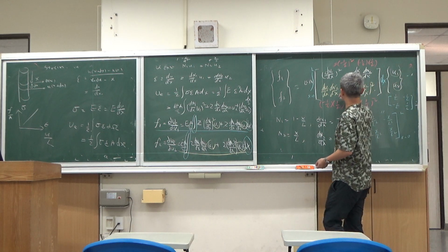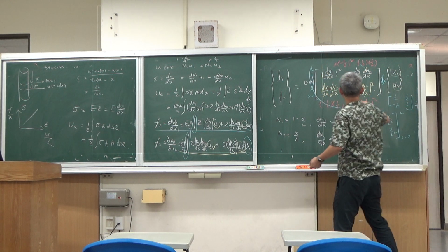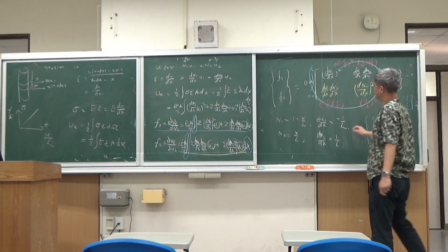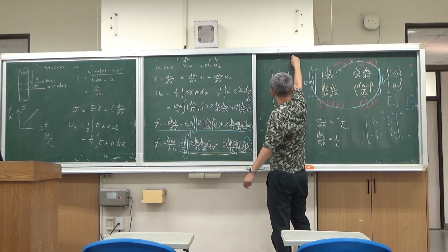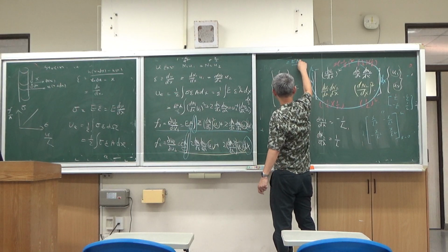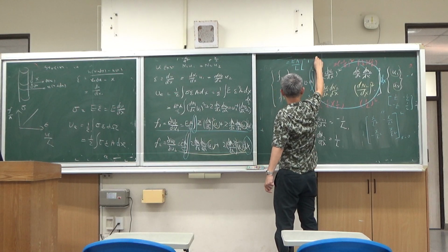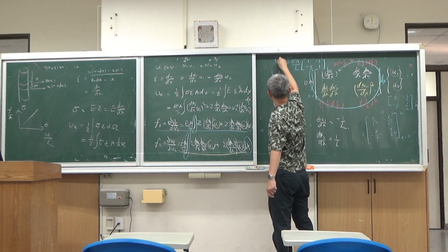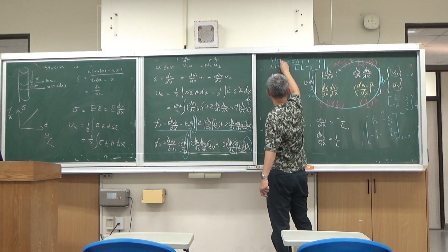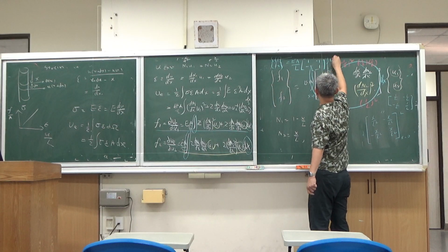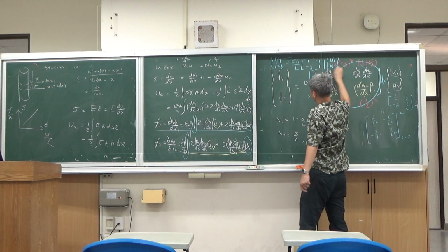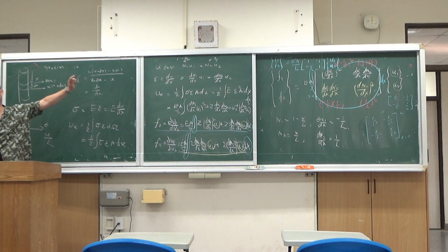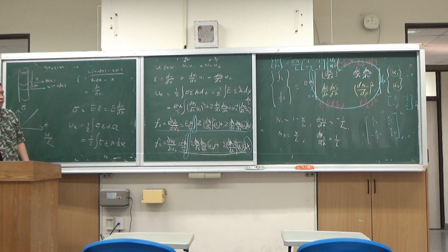If you do the substitution back, what do you have for this? If you take out the L, this whole expression reduces to EA over L, 1 minus 1 minus 1, 1. So this is now your truss element again, if you are using your energy method. Okay?